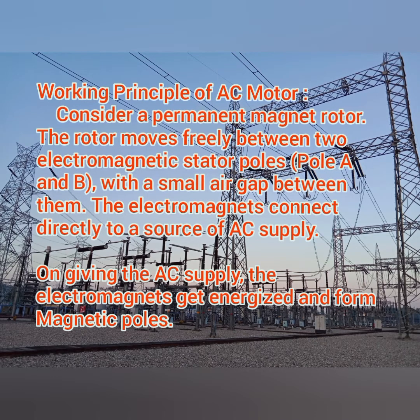Next is the principle of working. Now we are considering the rotor portion as a permanent magnet for the principle of working, and we have different types of rotor also. Here we are using the permanent magnet as the construction. The rotor moves freely between two electromagnetic stator poles, which are pole A and pole B, with a small air gap between them. The electromagnet connects directly to the AC supply.